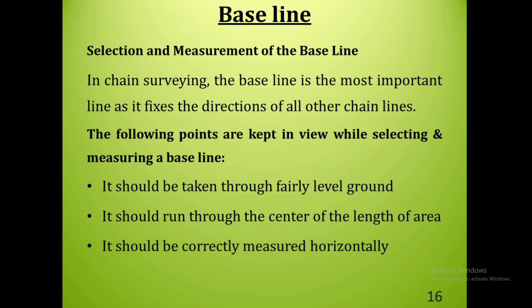Third one is it should be correctly measured horizontally. So in order to measure it, the chain or tape should be properly stretched tightly. Then it should be measured twice or thrice. In order to cross check it, it should be measured either twice or thrice.